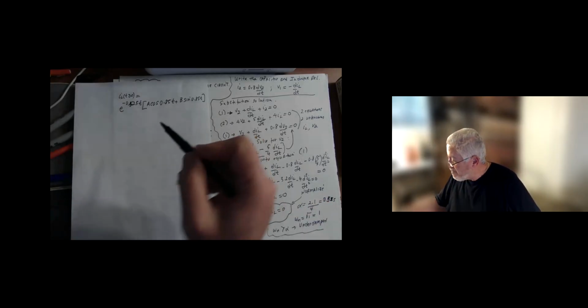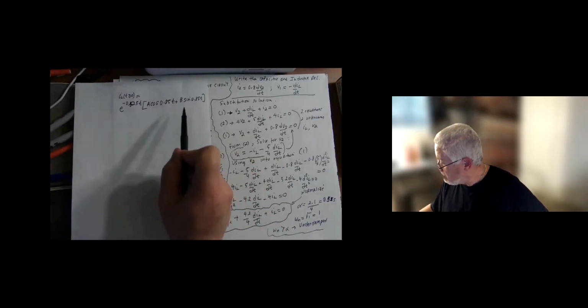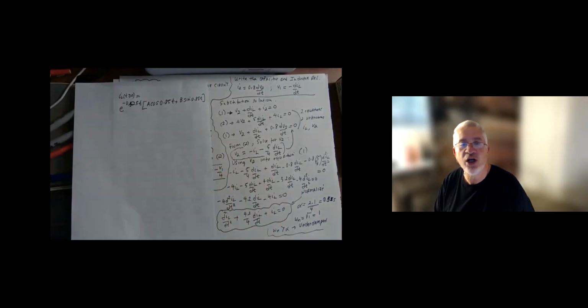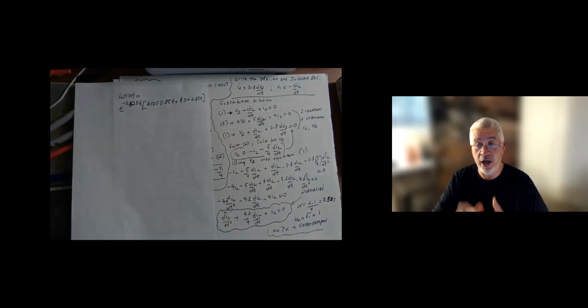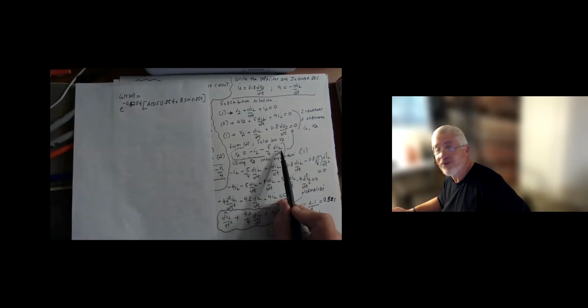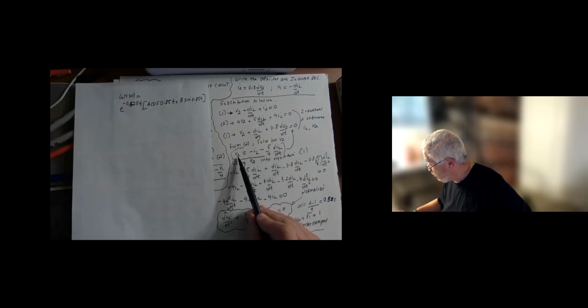And of course, our job right now is to calculate the two coefficients a and b, and we're going to use the initial conditions for a and b, essentially the initial condition on the current on the inductor, which is 1 amp, and on the capacitor voltage. You have got to remember the capacitor voltage is given by this. Okay, that is no small joke actually, to get the capacitor voltage from this, because you have to differentiate dIL/dt.